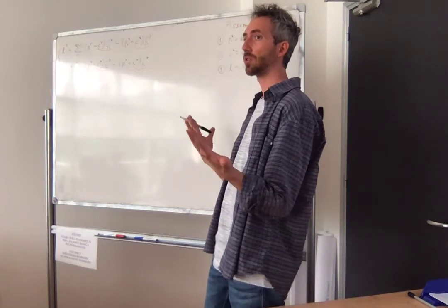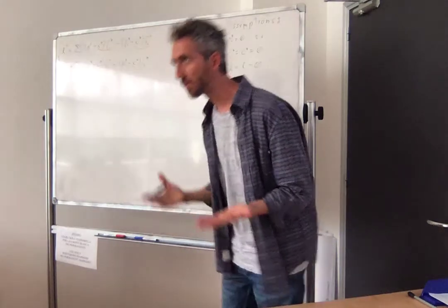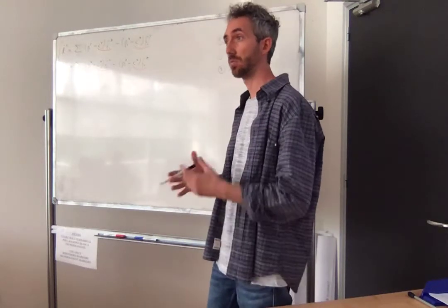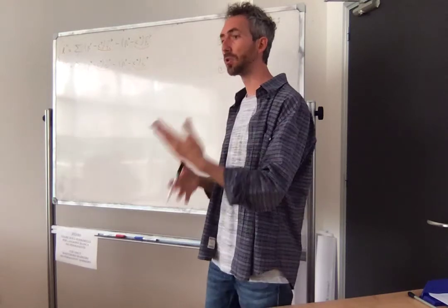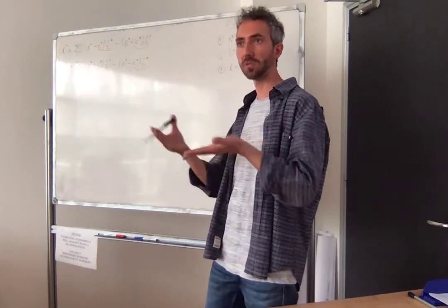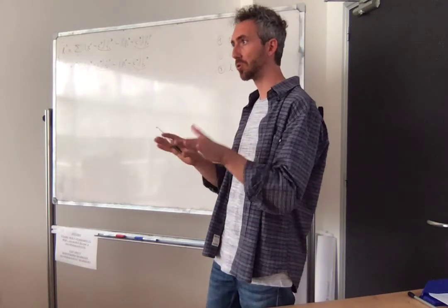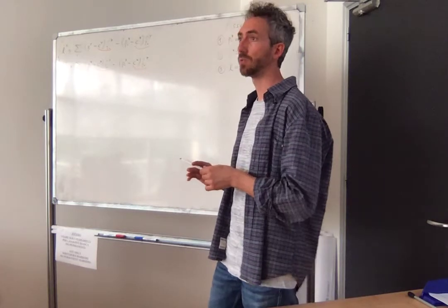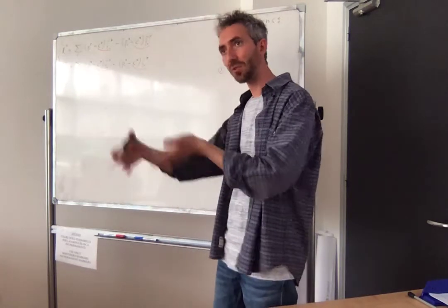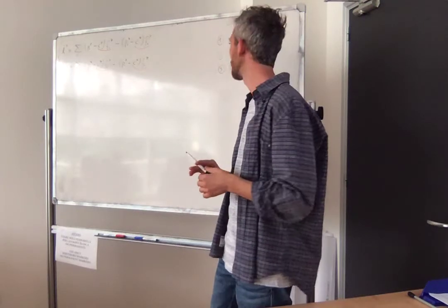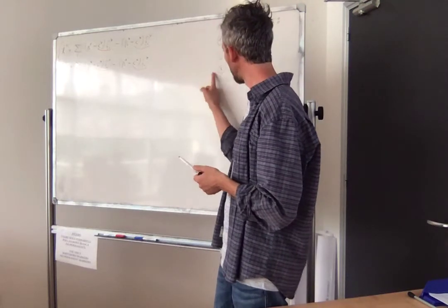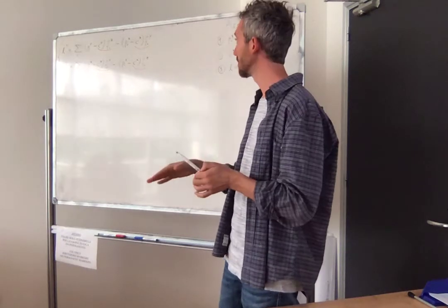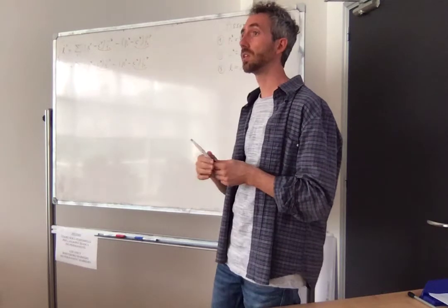Which means basically I'm not going to have fast angular movement of my trunk, my chest and my waist. Which again, for a human walking, has been shown to typically be the case. The angular momentum is kept very small during locomotion. Of course, if you want to do a backflip, no. But for standard locomotion, it is. So, exploiting these three reasonable assumptions for the context we are discussing, we can show that this equation will become linear.